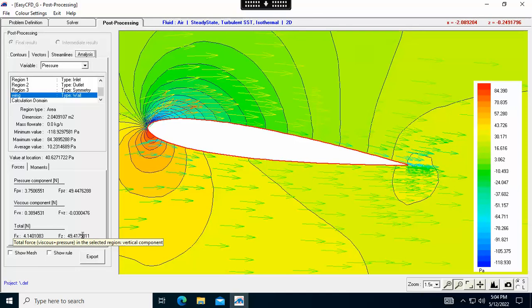So we'll be able to get lift and drag coefficients just using lift is equal to 1/2 rho v squared A times the coefficient of lift. All right, and then we'll check our results against published values, and we'll calculate those in the class. So once you get your lift force, you can calculate your coefficient of lift and coefficient of drag.